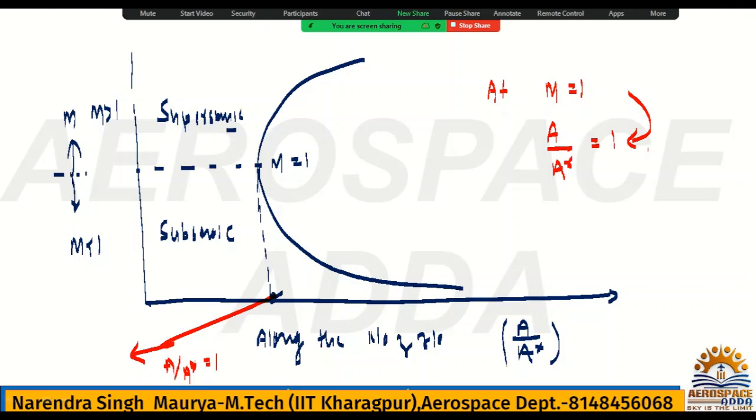Always remember, whatever the analysis you have done in the CD nozzle, last class I showed you 4 cases. Case 1 was subsonic throughout the CD nozzle. Case 2, just choked, means at the throat the Mach number reached 1. Case 3 was a shock wave inside the nozzle, and the fourth case was a shock wave at the exit of the nozzle.